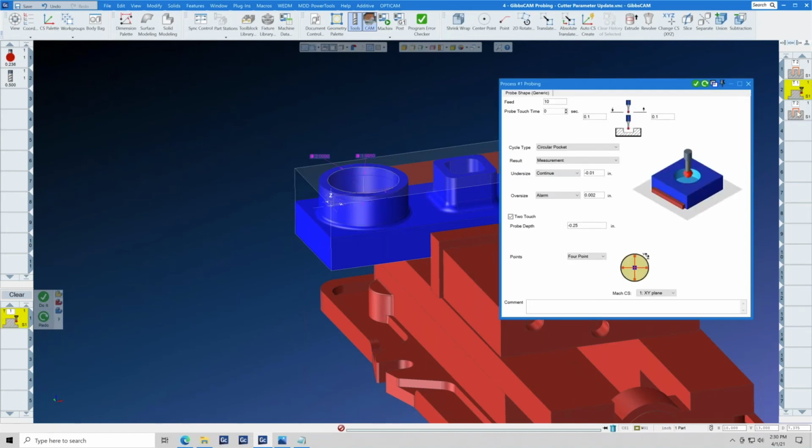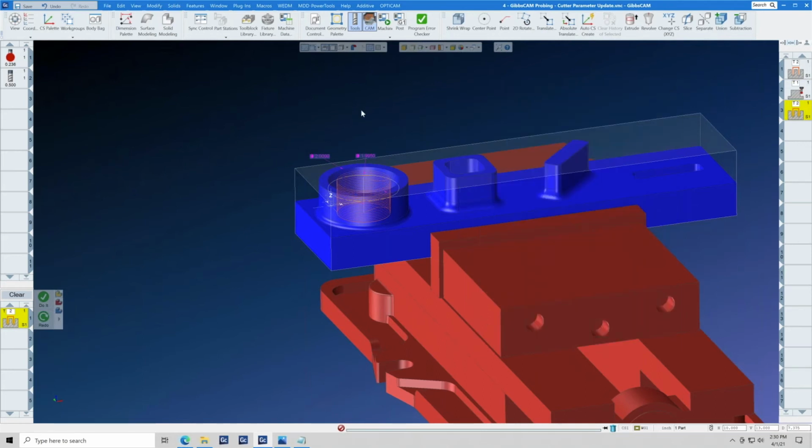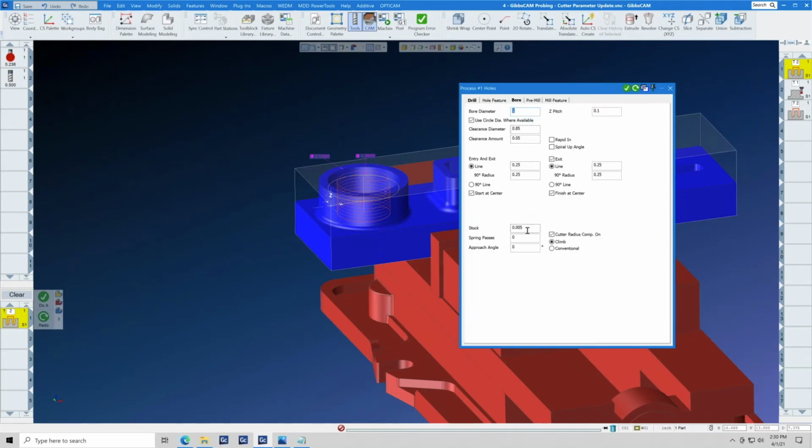adjust, cut technology. What we did here, we roughed out the bore, and then in op1, we semi-finished that 2-inch bore and left 5 thousandths on the inside of that bore.